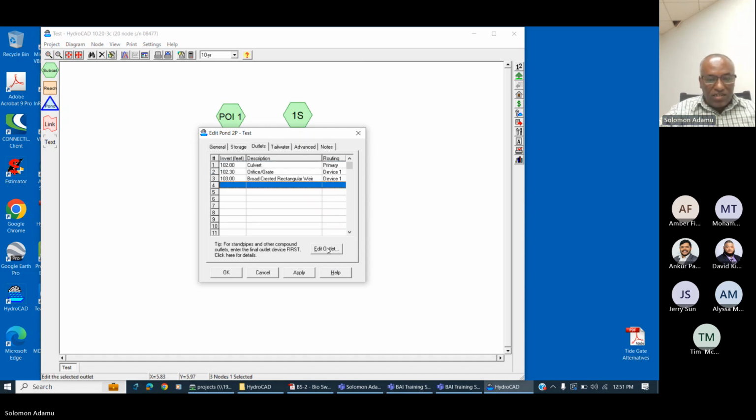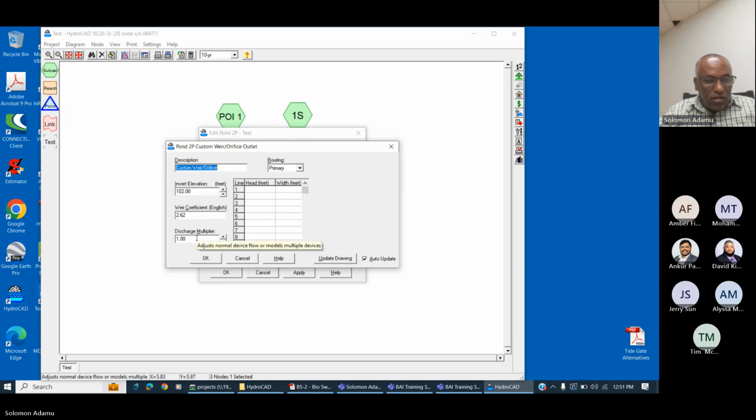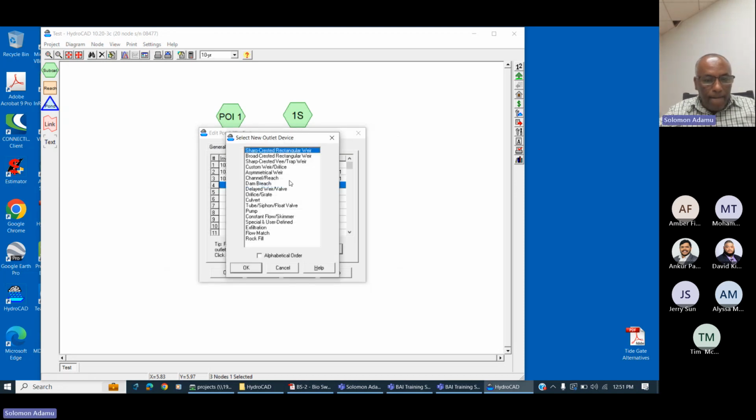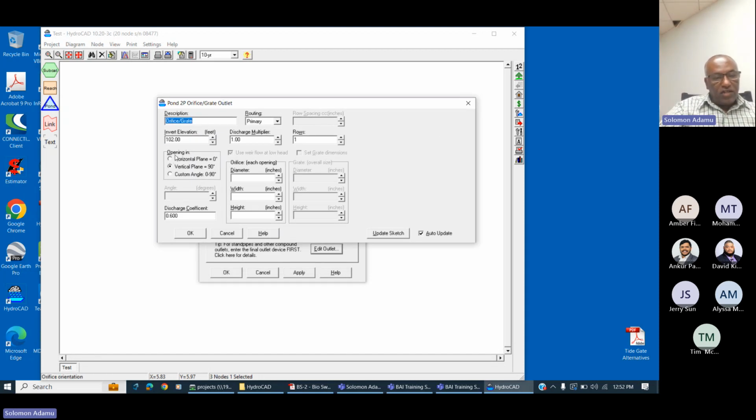Here I'm going to add a weir again. Weir or orifice. So Dave, to answer your question, that riser opening gets built into the program as either a weir or an orifice. Here it is. You now have the opening as horizontal, and I'm going to put the elevation at 1.5, and the size. And of course, if it is round or rectangular, you put that in.